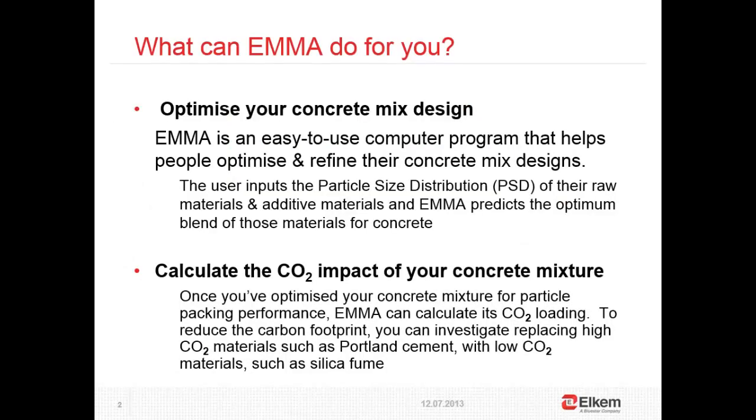The EMMA program is a versatile tool. It enables you to input your own materials and then check the balance of the mix design. It uses particle packing technology to give you the best blend of materials to form an optimum mixture for your concrete. With the correct input data for CO2, the program can even give you a figure for the carbon footprint of your mix design. This enables you to review the mix design to see if you can reduce the CO2 using materials such as silica fume.